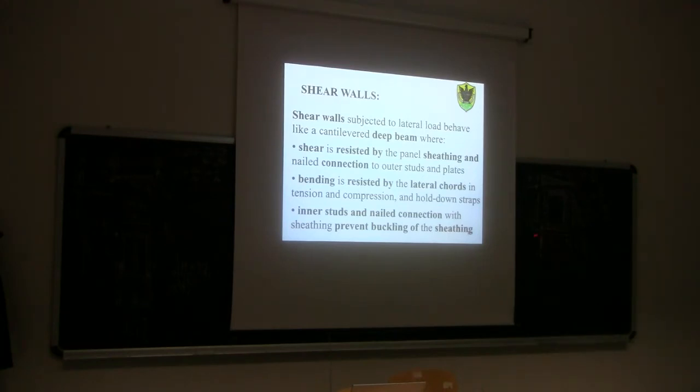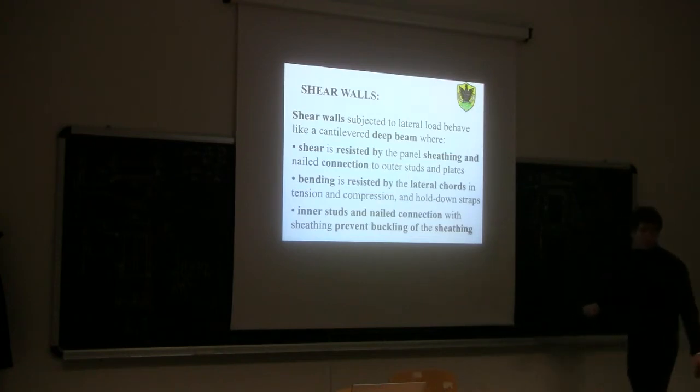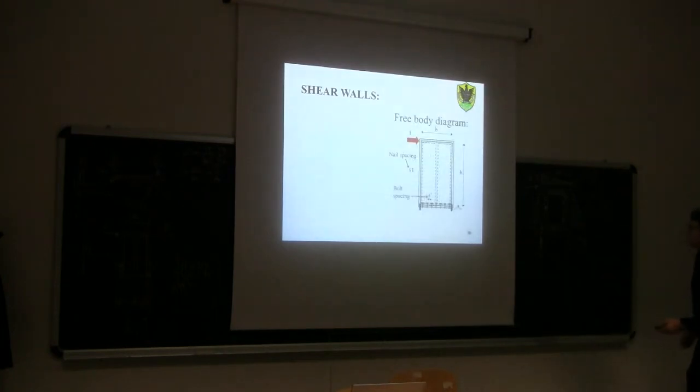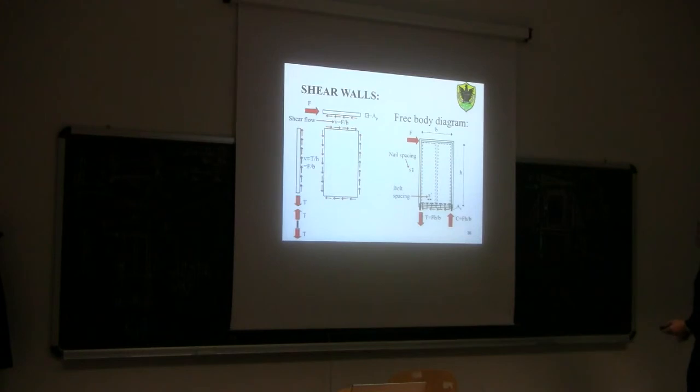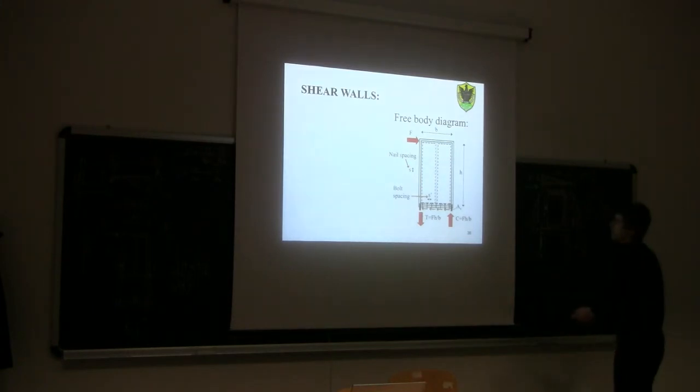Now of course, an important design value, now that we found out the value of the axial forces all around here, is the value of the shear in a nail, because then we will have to design the nail. So what is the value of the shear force in one single nail here? For example, let's call it with the right symbol. Let me find out what was the right symbol. FVD. Let's go back.